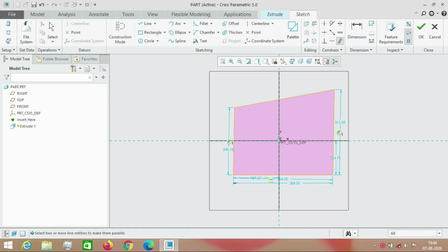That is not enough, so we make the other group of lines, this one and this one, parallel. Now you are able to get a rectangle. At times you may have to impose another constraint, where you make two adjacent line segments perpendicular.